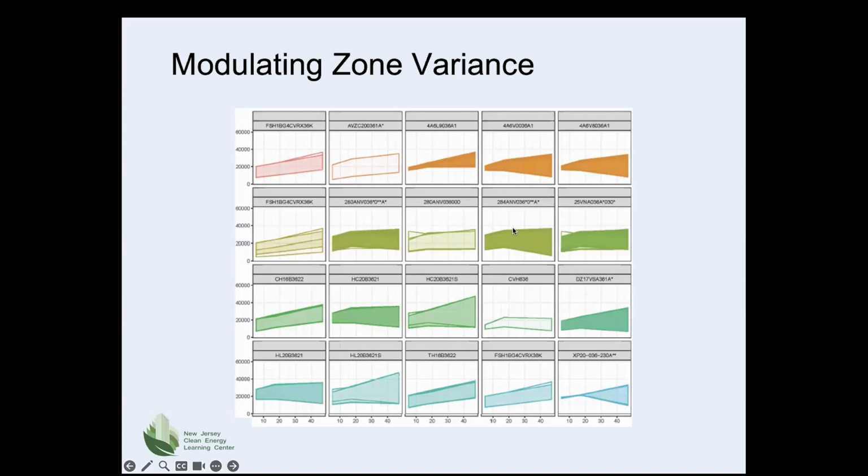And these would be other examples of that. And then some products actually maintain near nominal capacity, even at low ambient temperatures. This would be an example of that here. The bottom far left-hand graph is, you can see where even though it's at low temperature here at about 5 degrees Fahrenheit, it still maintains the capacity of almost 30,000 BTUs.